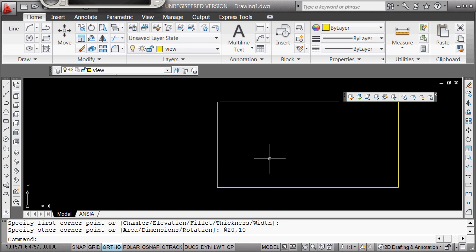And then you look at this drawing, and what they give you is the direction, one direction, and that is the direction AB, and the rest of them are turned angles, interior or exterior. There's a fundamental distance between direction and angle. Direction starts going 0, 90, 180, and 270 off a standard position angle. That is called a right hand coordinate system. Put your pointer in the X, your expressive finger in the Y, and your thumb will go in the Z direction.